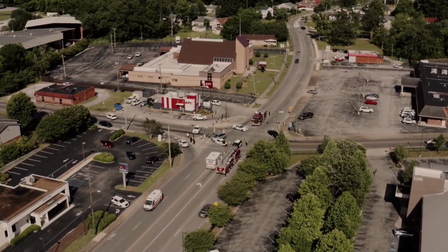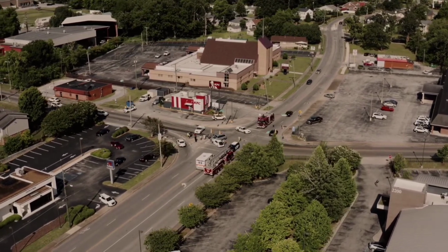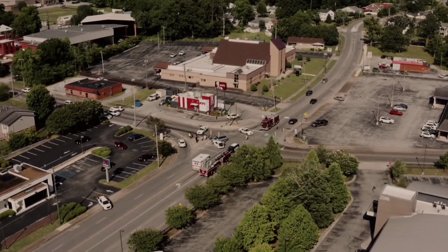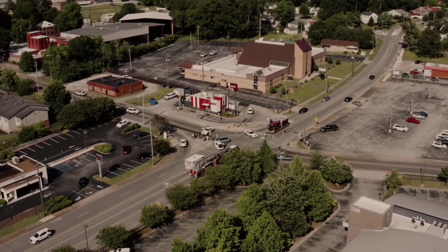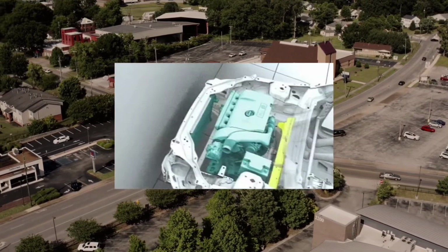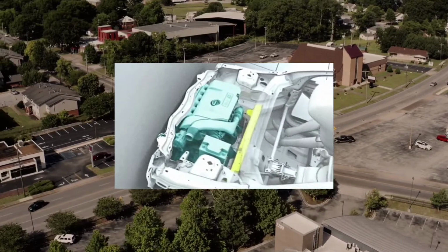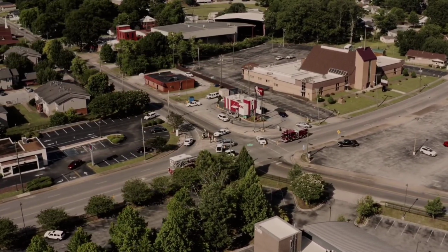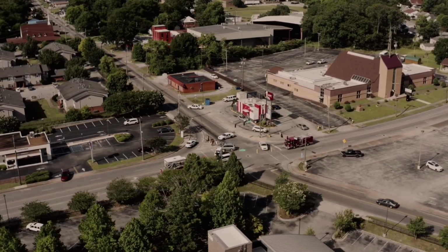In a crash, crumple zones help transfer some of the car's kinetic energy into controlled deformation, or crumpling, at impact. This may create more vehicle damage, but the severity of personal injury will likely be reduced. Crumpling allows the vehicle to take a little longer before coming to a stop, in effect lowering the average impact force and increasing the survival space for the belted passengers.